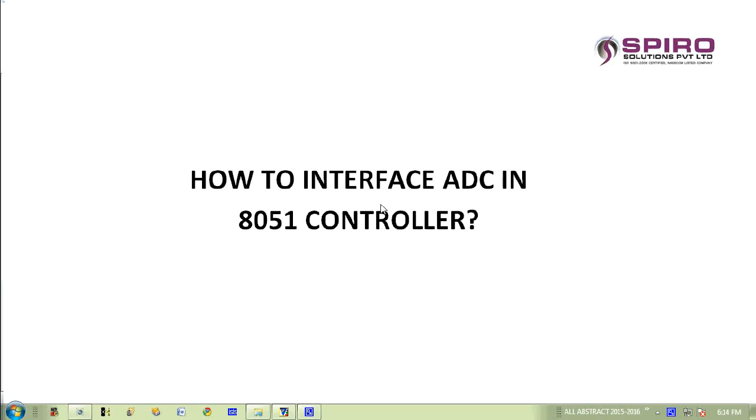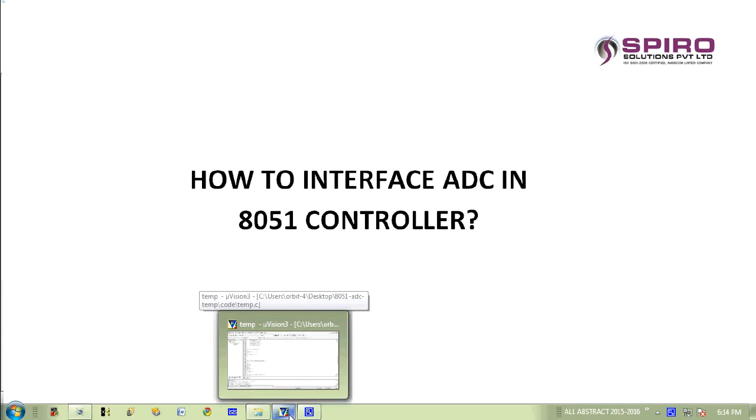Hi, now we are seeing how to interface an ADC with the 8051 microcontroller. Whenever we use an analog sensor, we need an ADC. The 8051 doesn't have an internal ADC, so we interface it externally. First of all, we will write the code for the ADC in the Keil compiler.